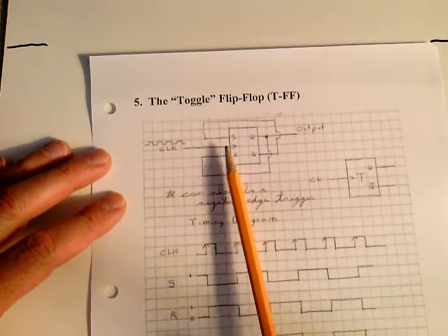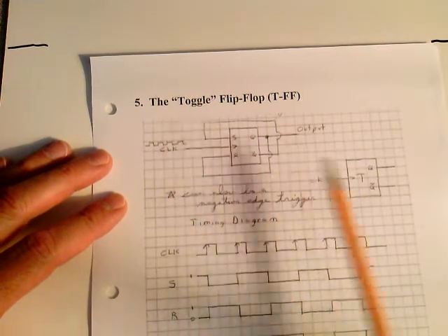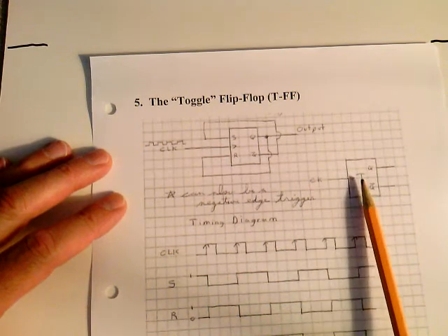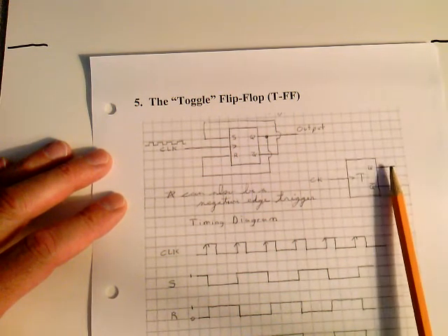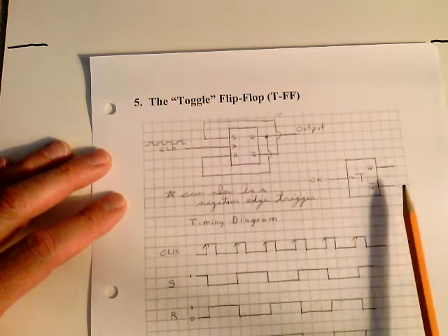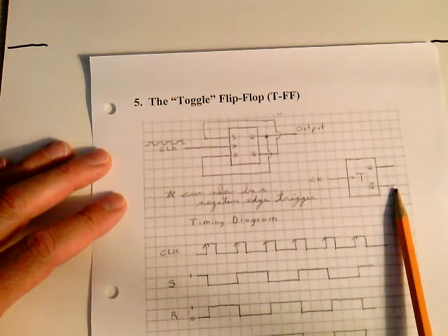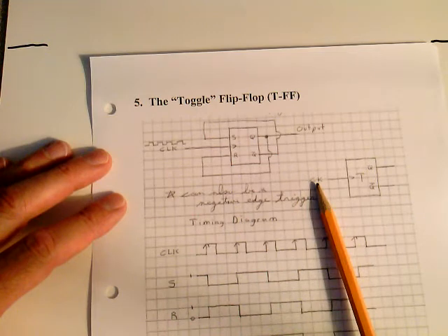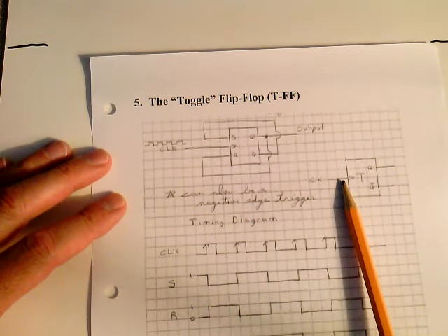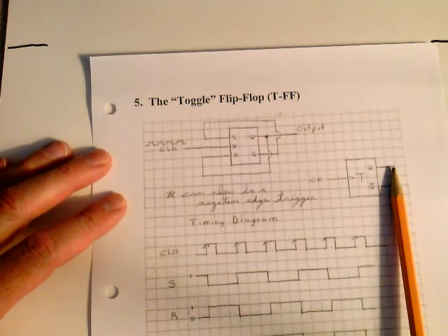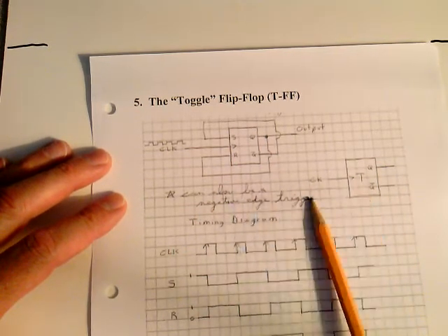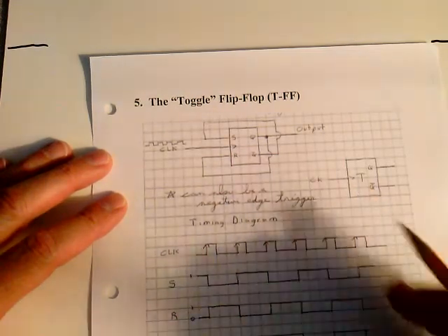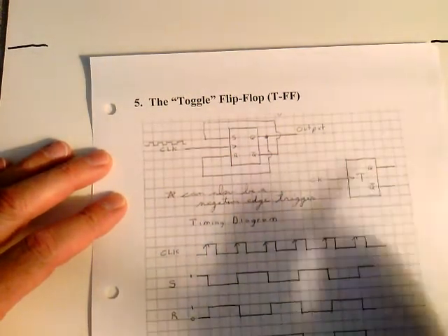The clock feeds in as one input, positive edge triggered, and here it is. Here's your positive edge triggered toggle flip-flop. It has two outputs. It has your Q output, and we're just going to talk about the Q output. Remember, the Q bar is just the opposite. So here's our input, clock, positive edge triggered, and it has a Q output. This can also come as a negative edge triggered flip-flop. You can put a bubble here and make it negative edge triggered.